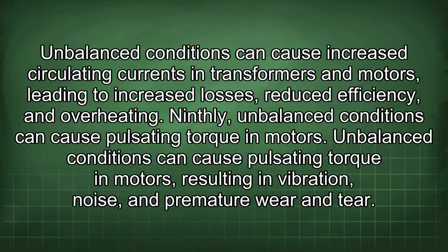Unbalanced conditions can cause increased circulating currents in transformers and motors, leading to increased losses, reduced efficiency, and overheating. Ninthly, unbalanced conditions can cause pulsating torque in motors. Unbalanced conditions can cause pulsating torque in motors, resulting in vibration, noise, and premature wear and tear.